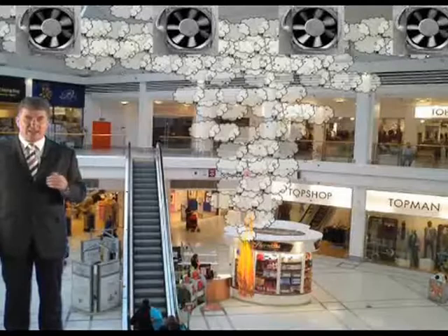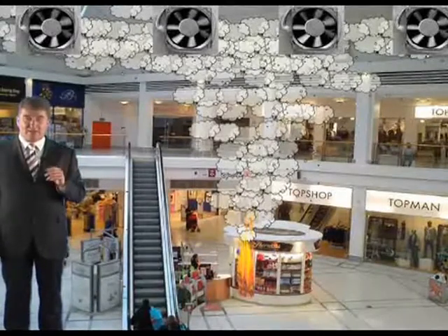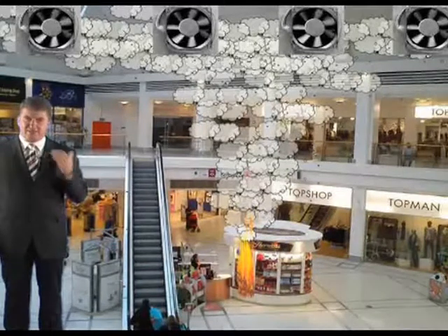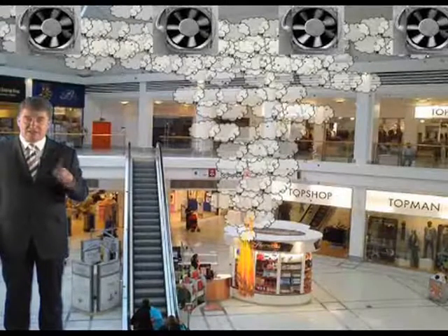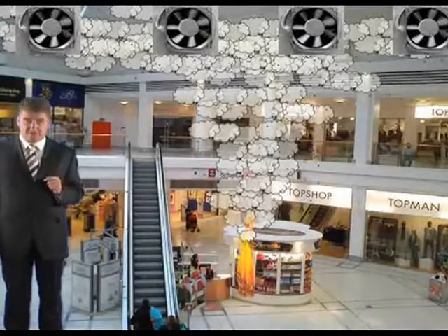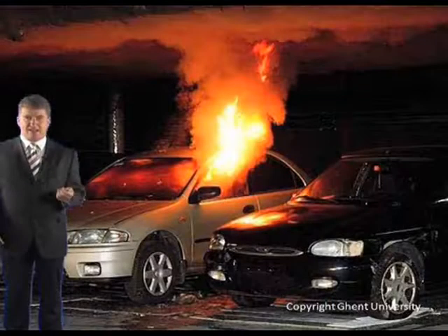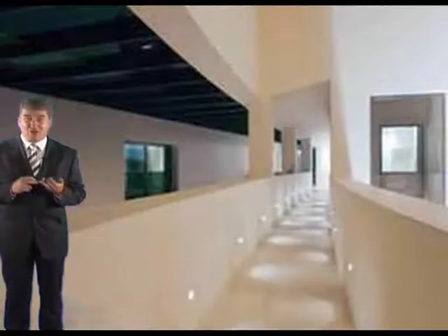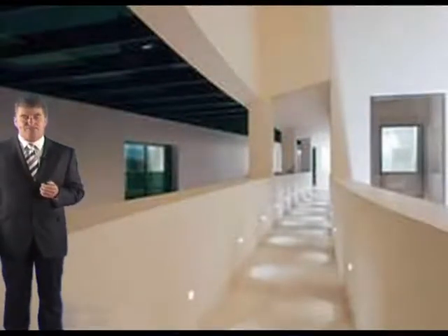Your hot buoyant gases from a fire rise to form a stable layer in a reservoir below the ceiling, such that a cooler, clear layer of sufficient height may be present for long enough to achieve safe evacuation of occupants. Other specialist methods of extracting, you've got car park extraction, residential flat corridor protection, and these are covered later in the presentation. Now, that covers the options available.